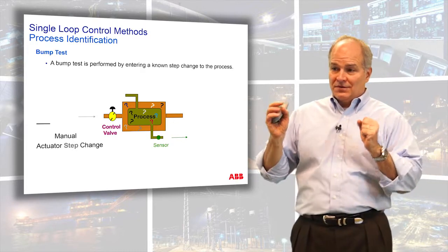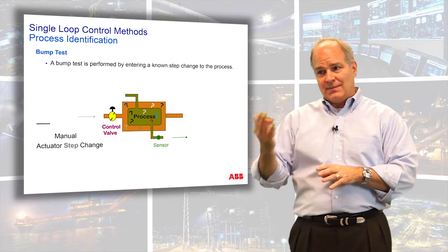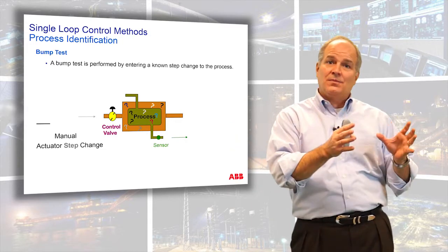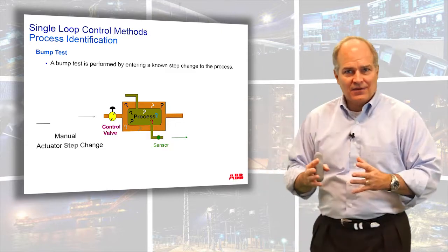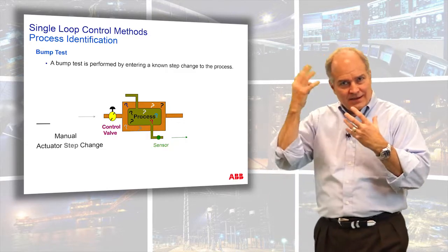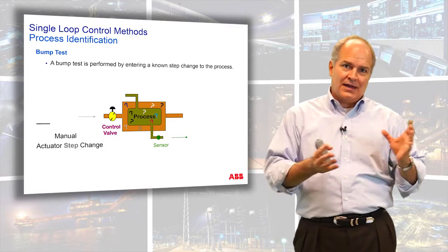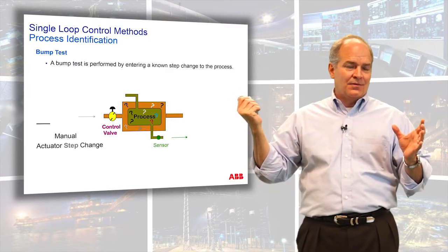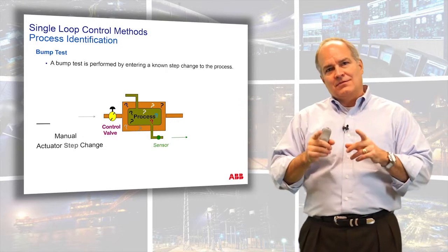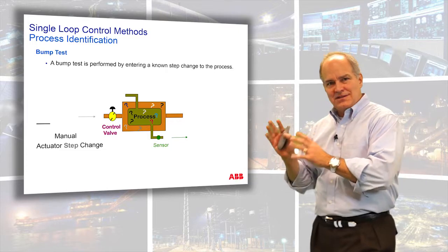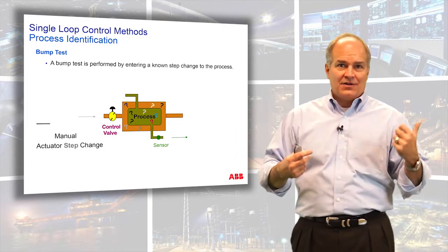And they said, well, here's the system, here's the control loop, we want you to tune it. And I said, well, before we do that, could you take me out on the floor and actually show me the instrumentation and actuation device? And they looked at me like, what? And I said, well, I need to see it. I need to get a mental picture of what I'm actually moving. And as I was walking out, the operator told another operator, when he didn't think I could hear, he said, this guy's going to fix the problem. Don't ever assume that you know the state of the actuator and the instrumentation. You need to take a minute. Have the operator show you.